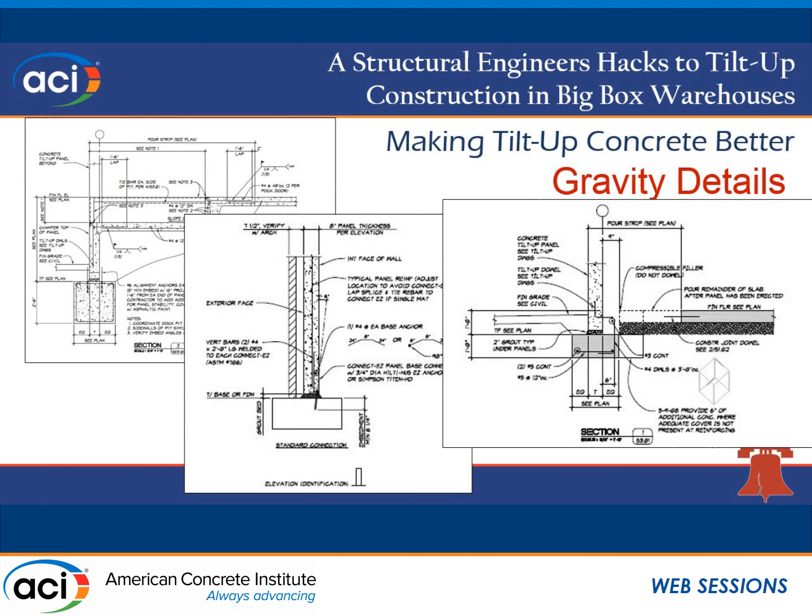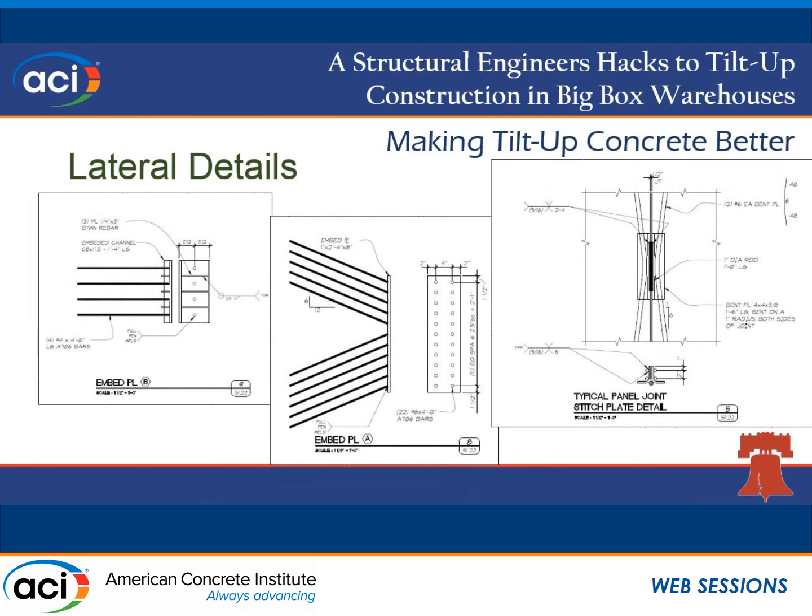I like the cast-in details where I can connect it. It's nice and redundant. High seismic loads, whether you've got an overturning issue here, where you're trying to develop a high point load reaction on the end of a panel, or you're trying to drag something into the panel. Using rebar to help develop into the horizontal reinforcement of the panel is a good way to get the forces across. The other one is the panel-to-panel stitch.